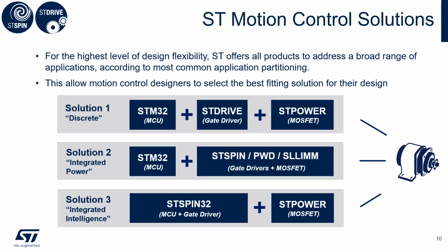We see the different approaches ST is offering to satisfy the customer needs. Depending on the application and mainly on the power output, ST is offering different solutions. Solution 1 is the discrete approach, where we have a standalone microcontroller, a standalone gate driver, and a standalone power section with MOSFETs.